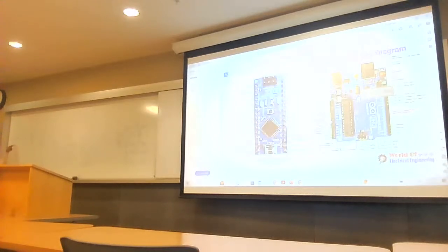Okay, and after that there are up and down signals. This is a charge pump. There are several architectures of charge pump, but if I draw the block level diagram, it works depending on the up and down signals. How do we get this up and down? These up and down signals are generated by this PFD depending on whether it is the same frequency or not. If there is any frequency change, we will get some up or down signal. Up means increase the frequency.